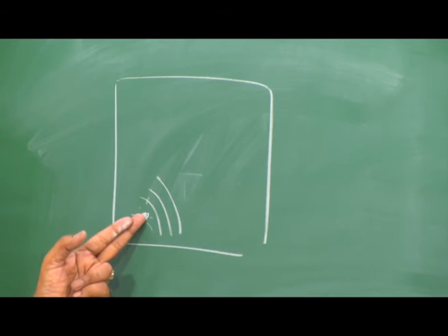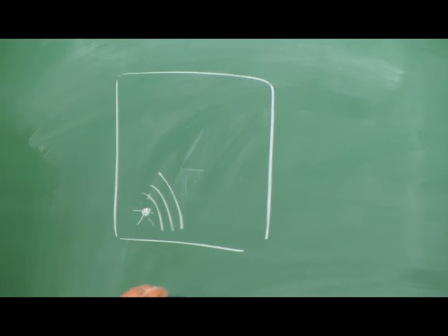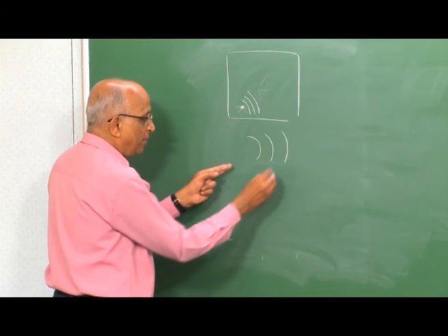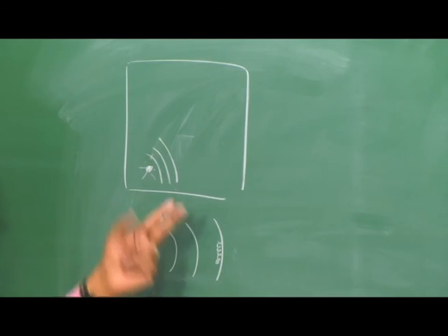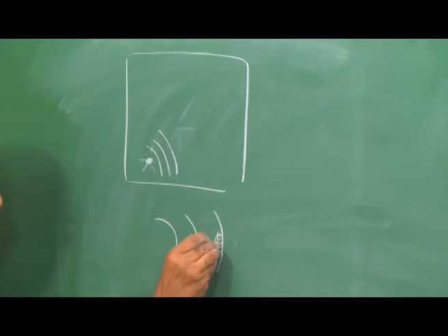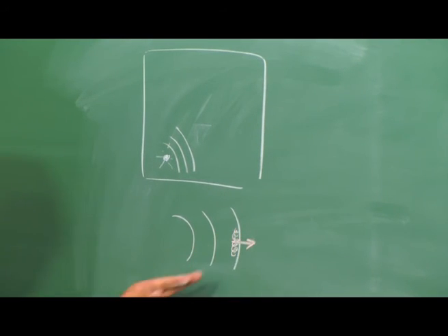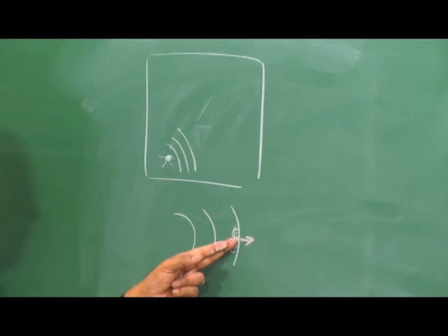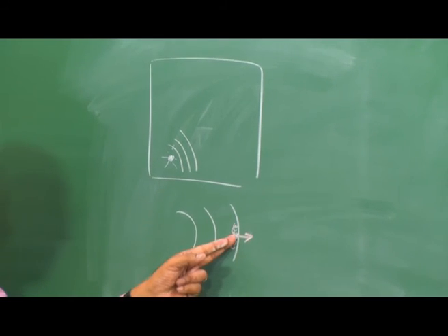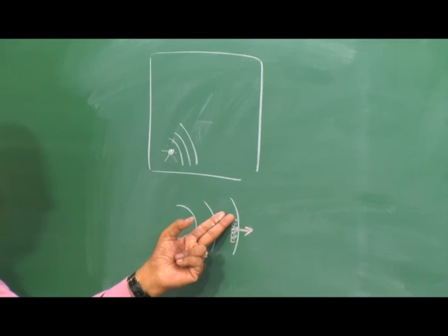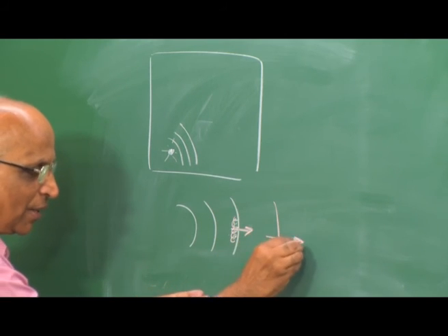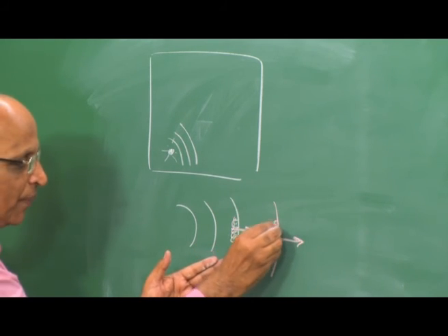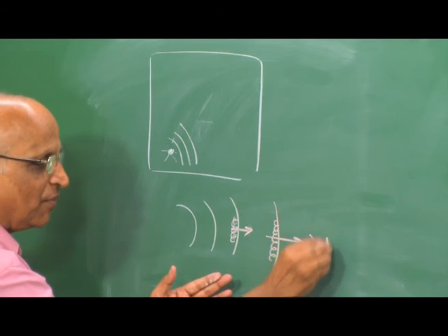But if the energy release is somewhat fast, sort of instantaneous, a shock wave could be formed, and behind a shock wave the temperature is quite large. If the temperature is quite large and it is an explosive gas mixture, the chemical energy which is released behind the shock wave could drive the shock wave, so that you get a shock wave driven by chemical reactions. If the chemical energy release is such that it can overcome the work done during expansion of the gases behind the shock wave, I can make the shock wave travel at a constant speed, and this type of wave is spoken of as a detonation wave.